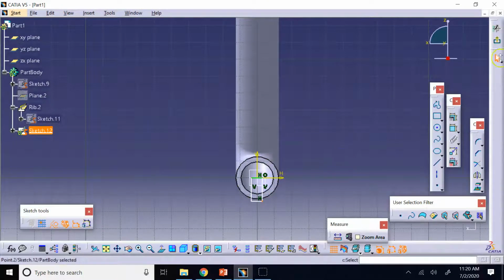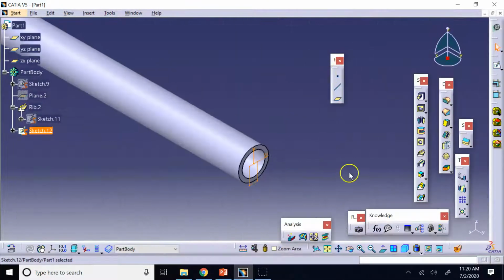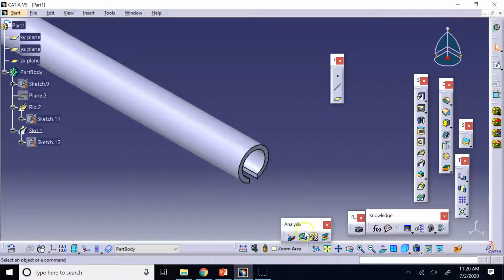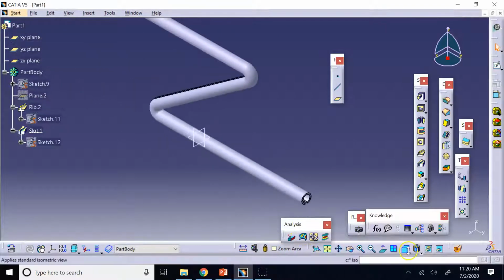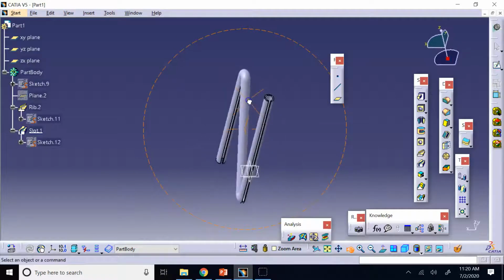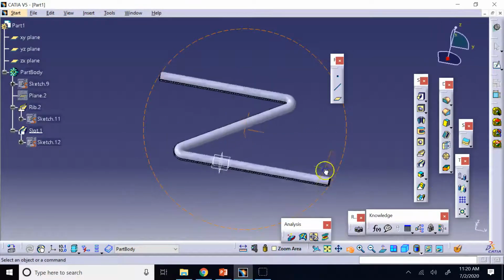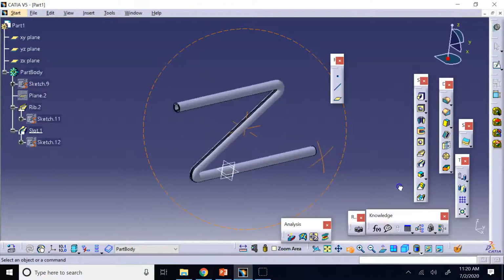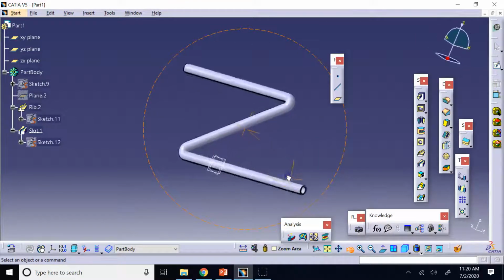So I bring it like here and try it one more time. If not, then we have to change this shape. So we do a cut sweep of that with this one. There we go, it allows it, and look now. Okay, so now you can see this cut is done through the whole object. So this is a cut sweep.